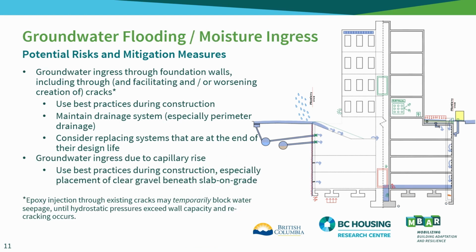Maintenance of below-grade drainage systems is also vital to limit potential water ingress. This in turn limits cracking of foundation walls for below-grade parkades or basements, which may result from hydrostatic pressures acting on the exteriors of the wall and exceeding the design wall capacity.